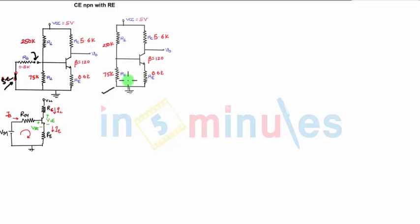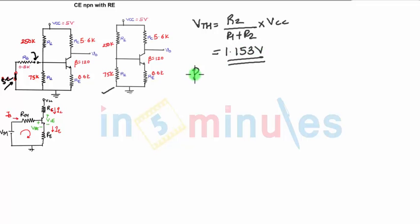So for this circuit, what we need to do is find VTH. How are we finding VTH? Potential divider rule: R2 upon R1 plus R2, into VCC. The values of R2, R1 and VCC are given in the question. So after solving, you should get this as 1.153 volts. Once you know VTH, we can find RTH, which is R1 parallel to R2. R1 and R2, 75K and 250K, are given in the question. So we can find RTH as 57.69 kilo ohms. So you have found VTH and RTH.